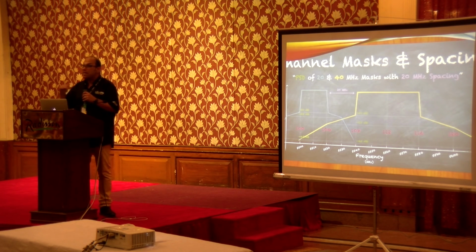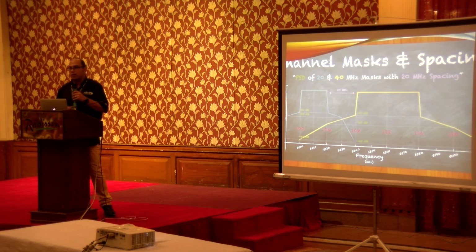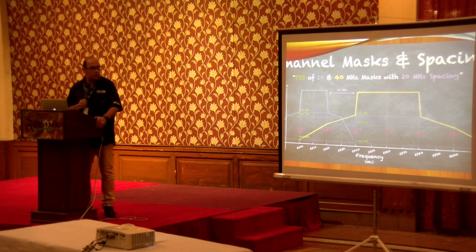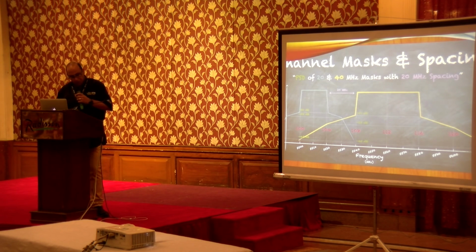But I'm telling you, the minimum is 5 megahertz. For sure, in saturated environments, you cannot find 20 megahertz free, but it depends on the environment. Minimum 5 megahertz needed.